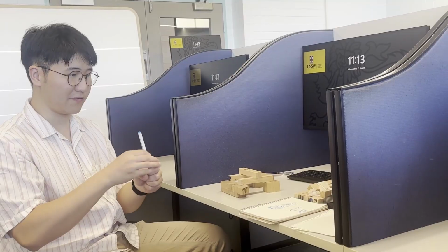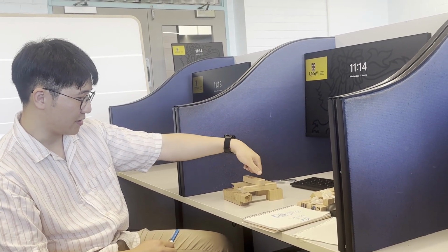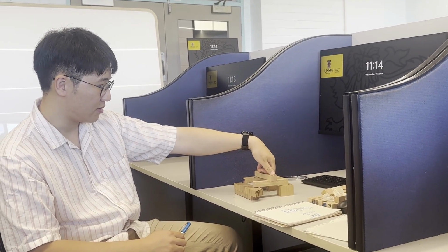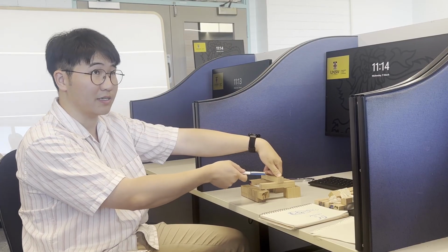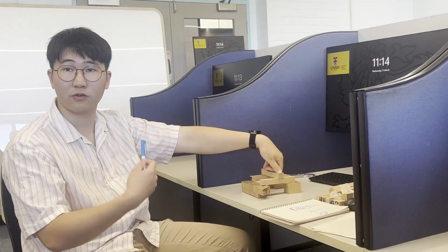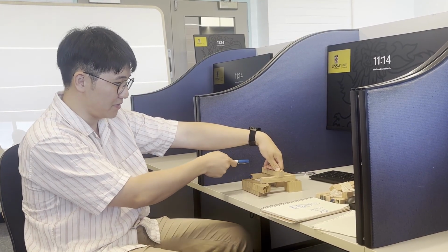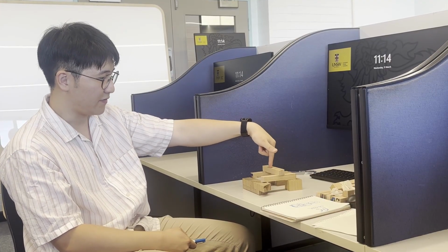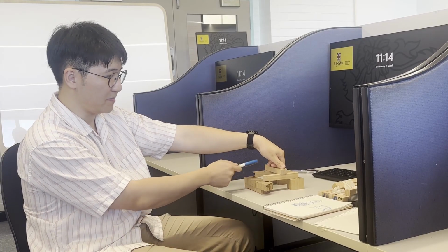In terms of industry knowledge, if you want to do structural engineering, that's the convention that people use. But what I want you to do is imagine this top beam is uniformly loaded. This could be on a roof, and this is like a mech deck, so it has heavy machinery equipment like aircon and cooling units, and it's got a uniform distributed load. I want you to first draw the bending moment diagram for the secondary beam, and then draw the bending moment diagram for the primary beams underneath it.